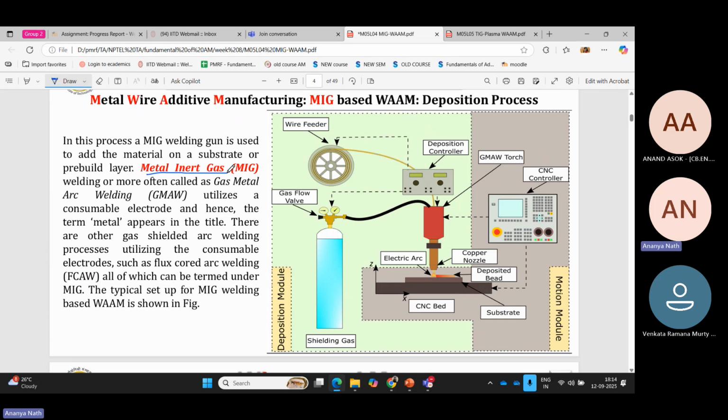And on the positive side, all the energy goes to the positive side. That's why, if you compare the negative and the positive side, the positive side gets more heat, because of which it gets melted. So in case of consumable electrode metal inert gas welding, we make the electrode, like the wire, positive. And when you're talking about the TIG process, that is tungsten inert gas, there my electrode need not be positive, because I don't want my electrode to be melted, because that is the non-consumable electrode.